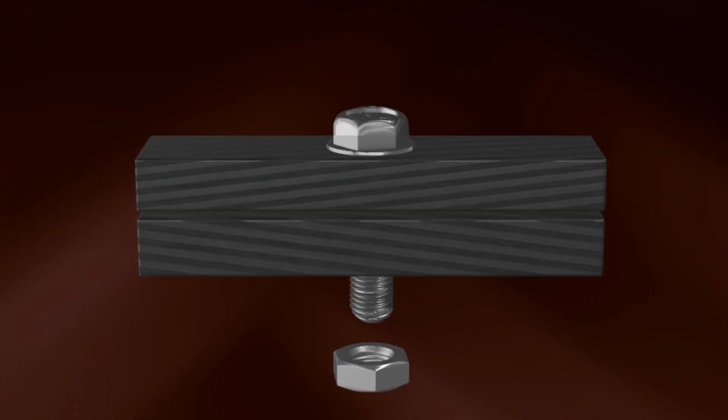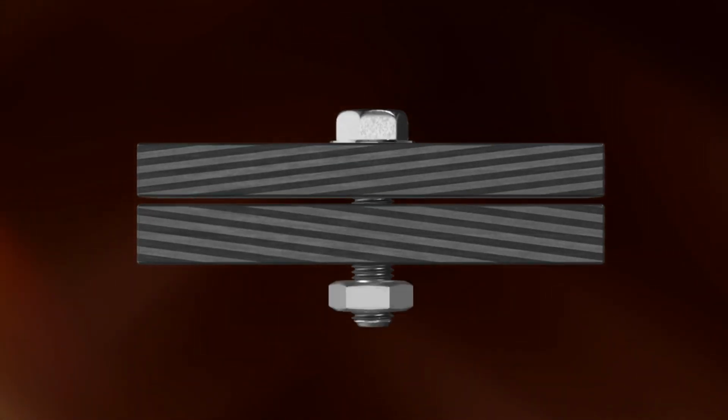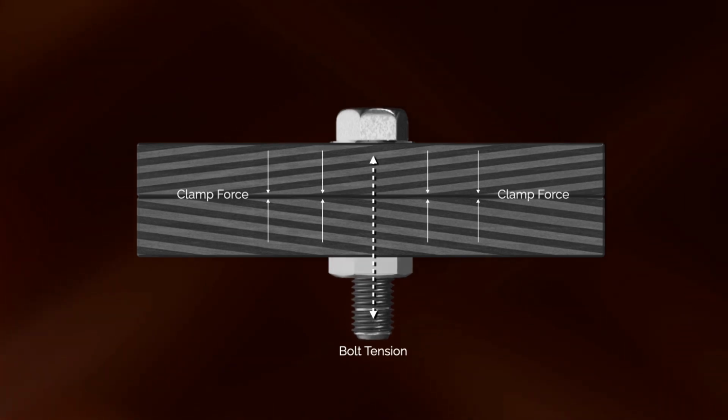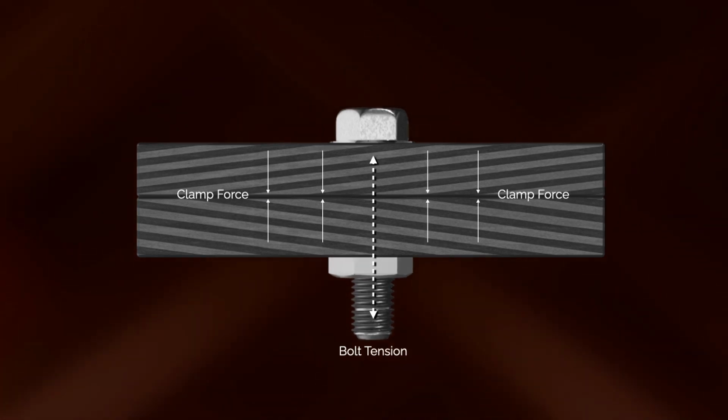This graphic helps to explain what we are doing while using torque. We have a bolted joint, and as we apply torque to the nut, it begins to stretch the fastener or the bolt, giving it bolt tension. It's this tension that creates the clamp force that we need to keep these components together without moving. This is the way that we achieve clamp force through torque.